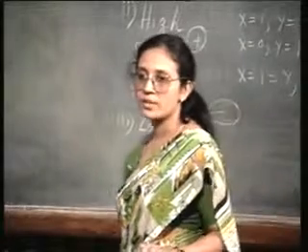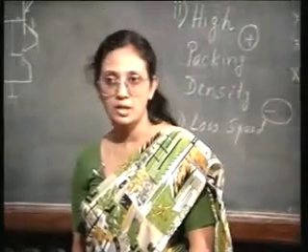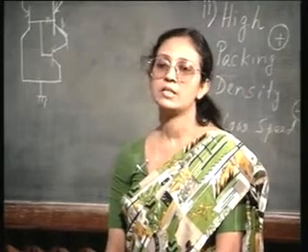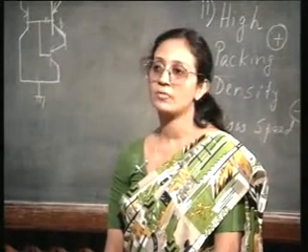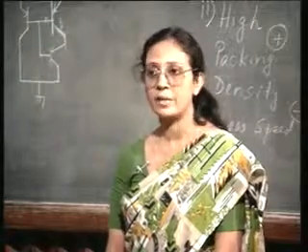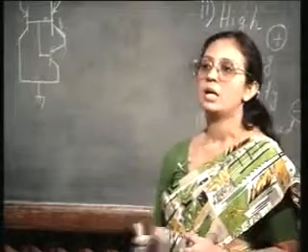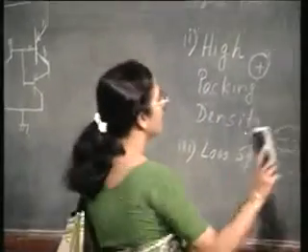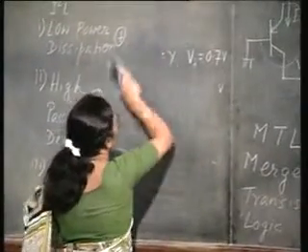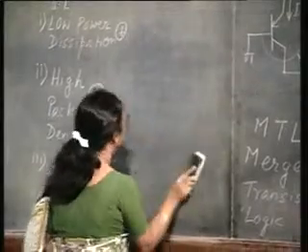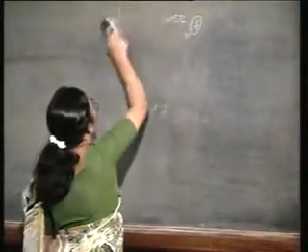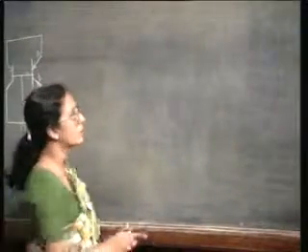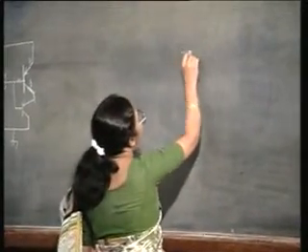And of course, as you have seen in case of junction isolation compared to dielectric isolation, if instead of junction isolation we have dielectric isolation, it is always better. So, a more advanced I square L design will be to replace the N plus collars by an oxide. So, in that case we will have a circuit like this.